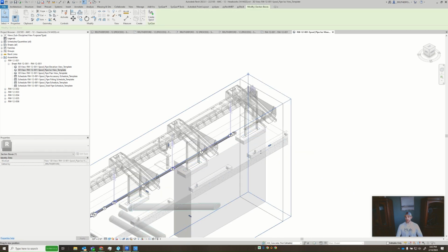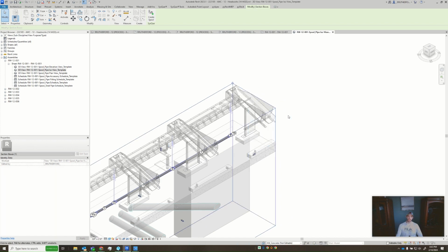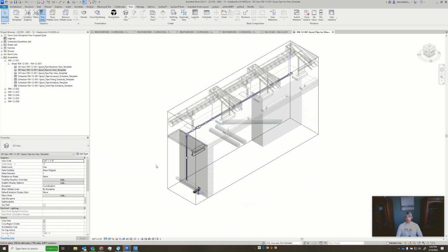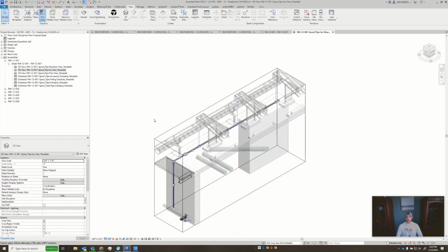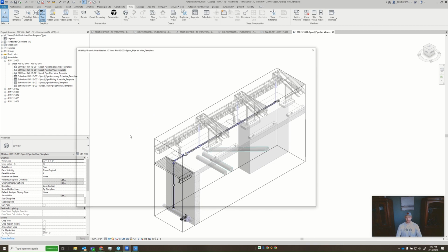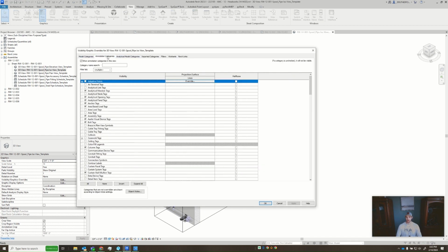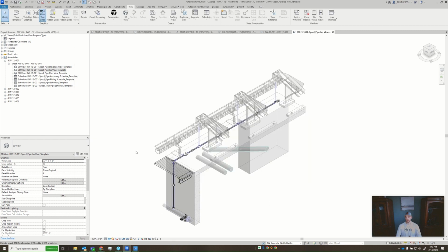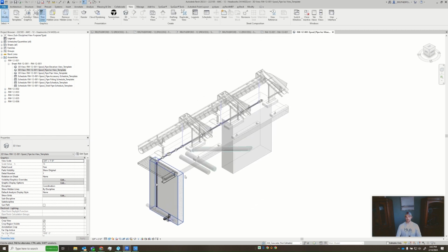I think that's a little bit too much information. It could be sticking out too far in my sheet. I just want to have just the right amount. And now that I'm happy with that, I am going to hit Visual Graphics Settings, VG, go to my annotation, SE for selection or section box, hit space, and I'm going to go ahead and take that off because I want to work with a fresh view. This is what I want to see.